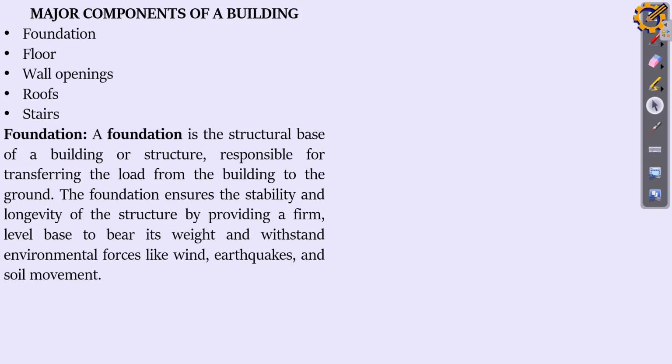Now the reason why you actually excavate your soil is to take away the weak soil so that you can have a more stable soil underneath. It is on that stable soil you now erect your foundation that actually carries the building.